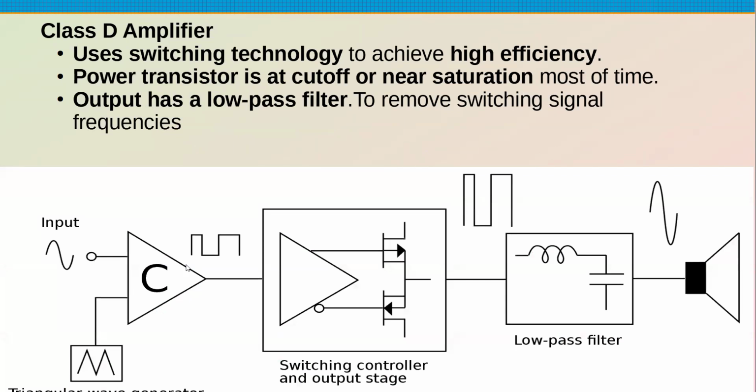Bob, could you explain what you mean by a tank circuit? A tank circuit is what we call a typically parallel inductor-capacitor circuit. It's called a tank because it stores the energy back and forth between the electrostatic field and the electromagnetic field in those two devices. And if there were no losses, it would just go back and forth forever. Gotcha. Thank you.